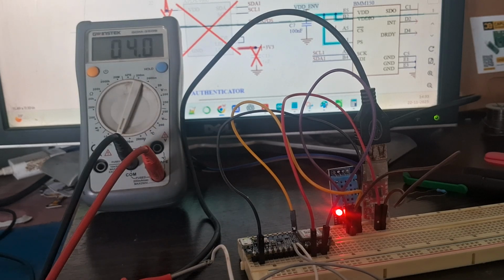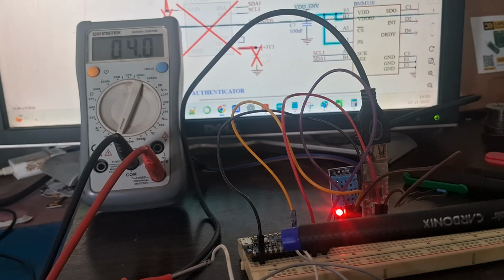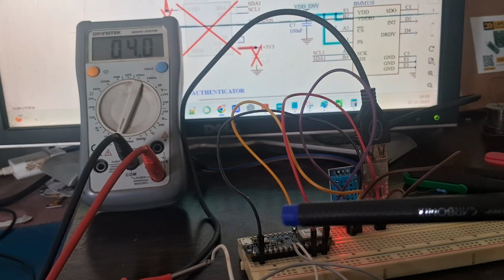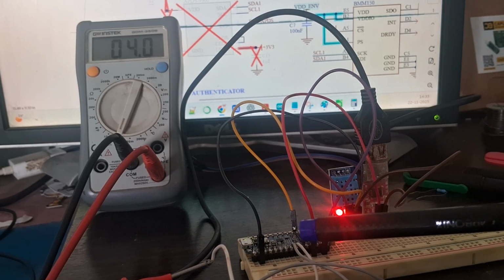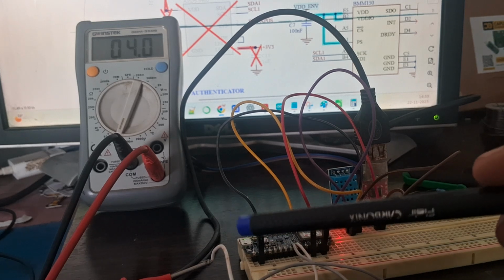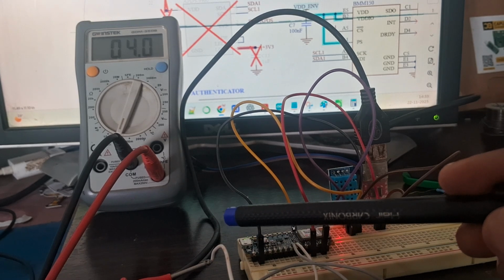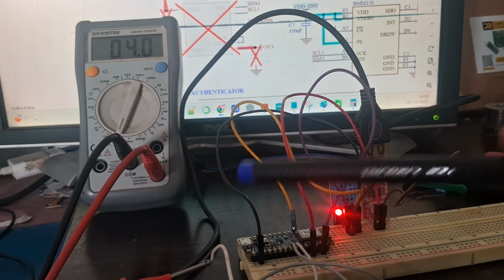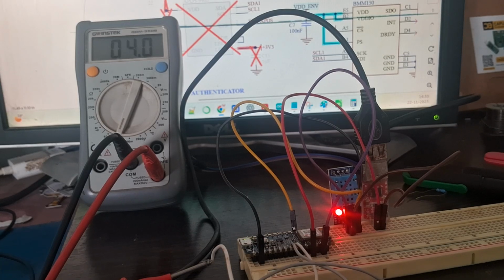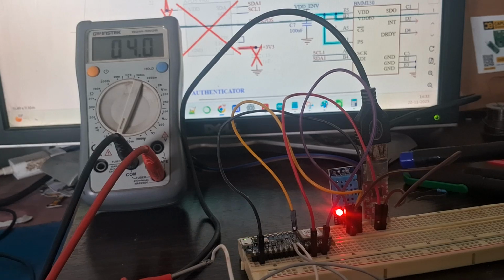So now in this video, we have an Arduino Nano board, okay? And on this Arduino Nano board, we are not just giving power directly from the USB. We are trying to give an external power. We don't have a DC supply, so if you are a hobbyist at home, you generally don't have a DC power supply, right? For that purpose, we have used a UART to TTL converter, which gives 5 volts on one of the pins.